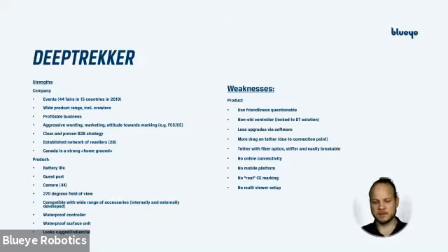I also believe that the tether of Deep Checker is built on fiber optics, which is stiffer but breaks easily. This is not 100% information for me, but we use double wired copper, which is more durable. So when fiber optics breaks, it breaks, then it's done. As in double wired copper, it lasts longer and it kind of degrades. So you'll start to see signals of weaker performance, but it won't break at once.